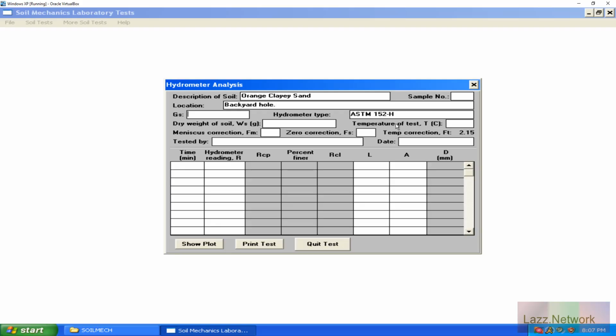And as you take your readings, you are also going to record a temperature, because of the specific gravity of water. Obviously, if your water is hotter or colder than it needs to be, it's going to greatly affect the position of your hydrometer, and you might need to apply a correction, which technically you would have already done from calibrating your hydrometer initially.